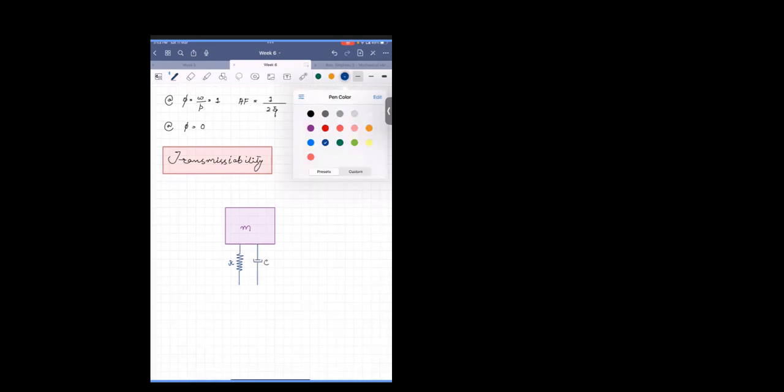So for our convenience in the mathematical modeling of our single degree of freedom system, we show it like this. And this dashpot is also just a mathematical representation of how the damping looks. Here we are using only viscous damping, but in our actual structural systems, the damping is because of friction, the drag, the friction between the joints, and all the other factors. So if it's k and c like this, it's supported on a system like this.